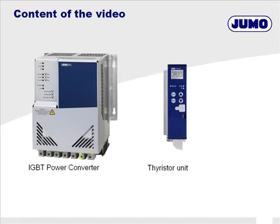The IGBT power converter, as well as the Thyristor unit, are used for electric heaters with higher standards concerning the quality of control. To feature the advantages of the IGBT power converter, first of all, we would like to describe the functionality of a Thyristor unit. The main differences between the systems arise from the operating modes.